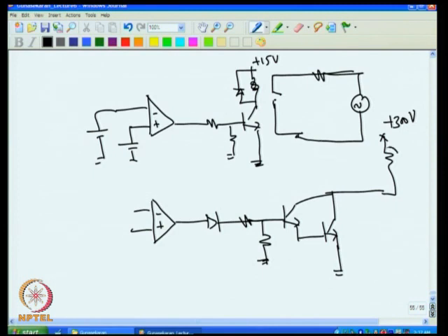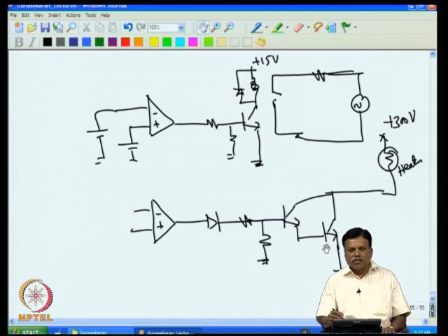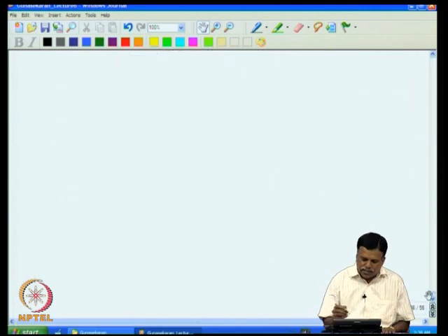So this can be a heater, and this can be high voltage and high power, because even the 15 volt coming here can switch this on, and this voltage can be even 300 volt or any amount of voltage. The only condition is that this transistor and this transistor should withstand the VCEO breakdown, then only this can work. So this is easier to write. Or we can also use, for example, a thyristor.